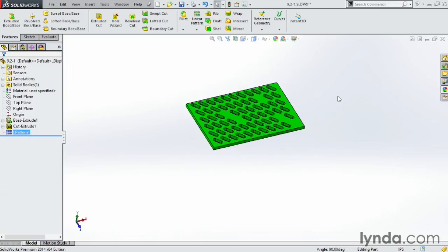Patterning can be done in the sketch mode. However, that creates a large, complicated sketch, and it's much harder to work with. I always recommend keeping your sketches as simple as possible and patterning and mirroring bodies and features versus sketches. The results will be the same, and there are no rules. However, feature-level patterns are so much easier to work with.